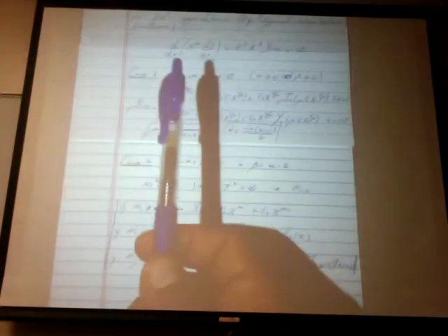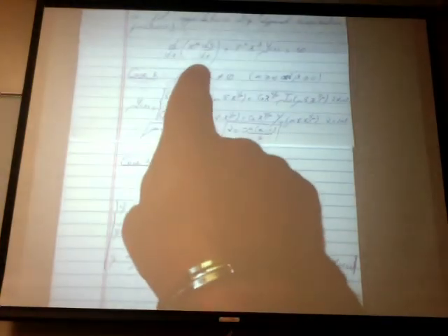And the alpha and beta are related to the cross-section area decay of the fin. So by optimizing this equation, you might end up with a fin that looks completely different from what you had imagined. Okay? Well, the first attempt is to make it triangular. A triangular fin is a specific form of this equation, which will lead to a solution in terms of K0 and I0. All right. Any questions?